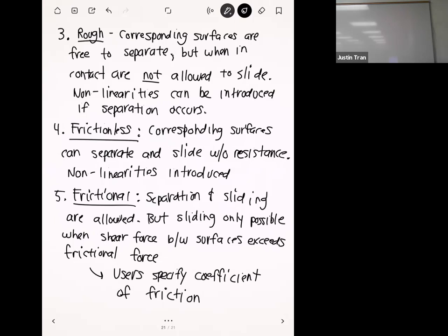You might change it to pressure, because the pressure load gives you the option to apply it to a circular surface like this, and it ensures that the force is going to be uniform. I think that's more realistic for a clamp, because right now you're just applying a force. Okay. Yeah, which you can do too. If you want to do a clamp, then I would do it. Okay. Sounds good. Because that's kind of what's happening, fixing your clamp.